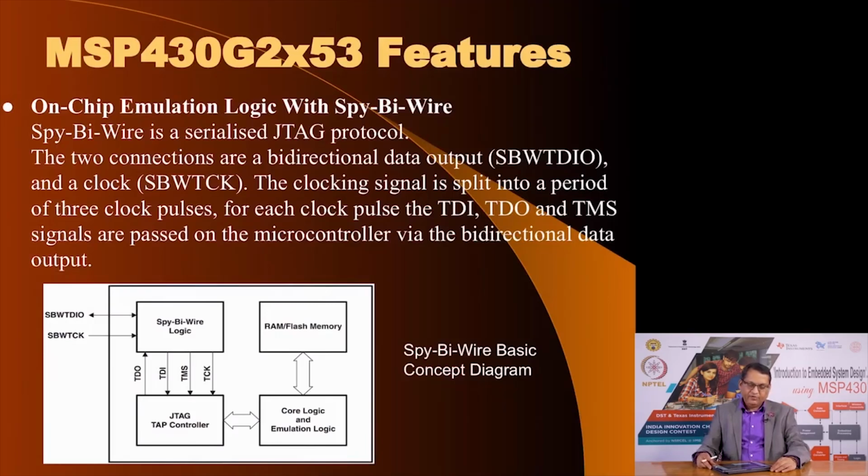Let us see some more features. It offers you on-chip emulation, which means once you have downloaded your program, you would like to evaluate how it is functioning, and it uses a Spy-Bi-Wire protocol, SBW, a name that Texas Instruments gives to its serial wire debug, called Spy-Bi-Wire, and it is actually a serialized JTAG protocol.